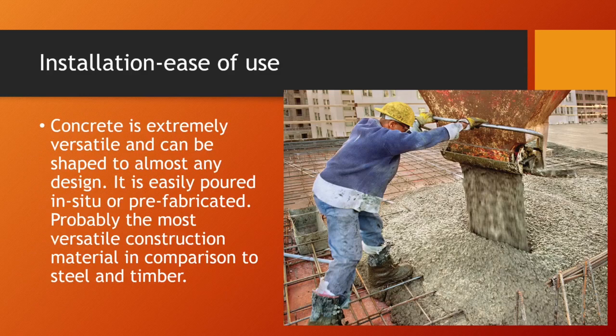Installation, ease of use. So this is live concrete being poured, and then you can see, of course, there's the regular steel, your man standing on it. It's something I've done a lot of. It's poured in place, and then the pokers are plonked in between all these squares, all these steels, and then obviously the air pockets are vibrated out. So it's a very flexible form of installation.